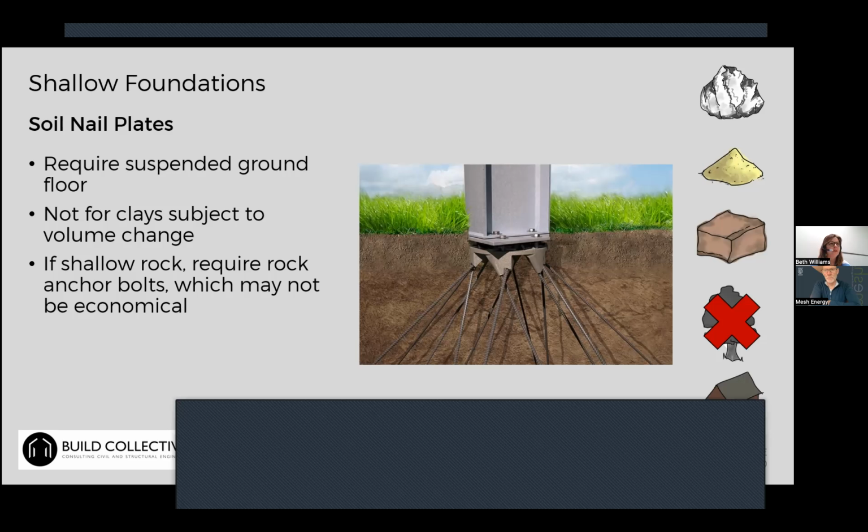Yeah, but we do have processes. If it's a new build house, like a Grand Designs type of house, which is a lot of what we do, bespoke new build houses, we will usually want a site investigation from a geotechnical engineer, particularly if it's in our local area, because we know there's lots going on around here. It does slightly depend on where it is in the country. If it's not that local to us, we might want to chat to a geotechnical engineer who is local to the site, who might know more about any local issues.